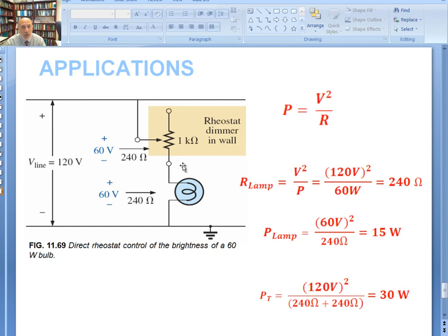So that's the whole purpose of putting a controller switch in there, the dimmer switch, with a triac and a diac, and with a capacitor and inductance. Number one, to protect against any spikes. Also, to filter out all the noise coming in from the trigger switch, and plus you're not dissipating energy inside a dimmer switch. All the energy will be in the lamp at the high and low end of it. All right, that's one of the applications of that.